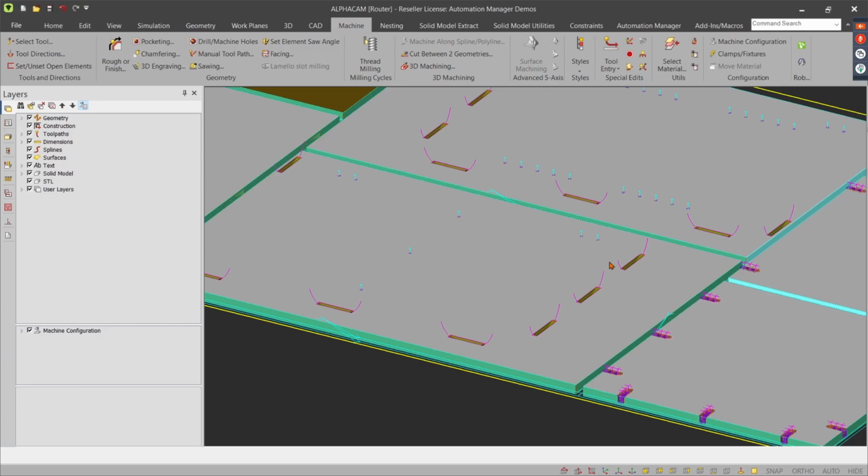It's quite a complex toolpath to create, so we made a macro for you to take away and use. Extremely powerful. It does 3-axis, 3+2 with a saw, and also 5-axis simultaneous, automatically generated, depending on how you want to machine it, what machine you've got, etc. So it's a nice feature to add in there.